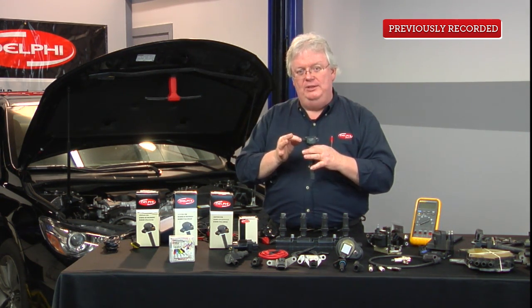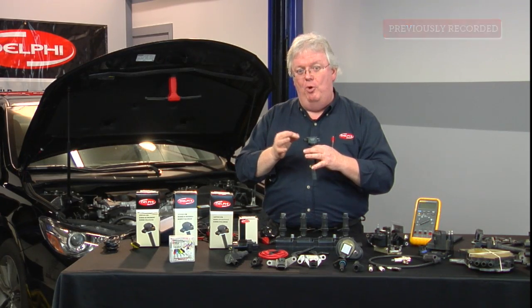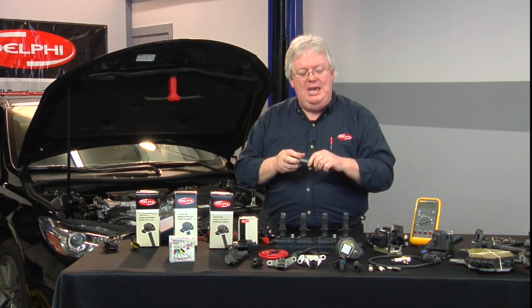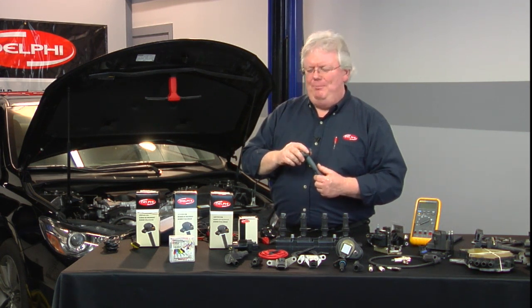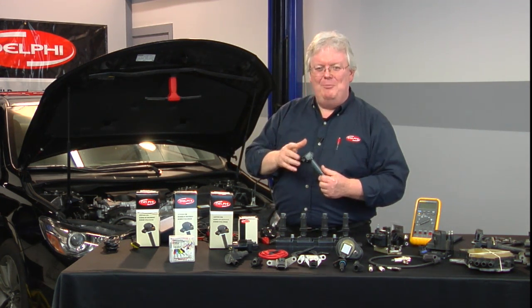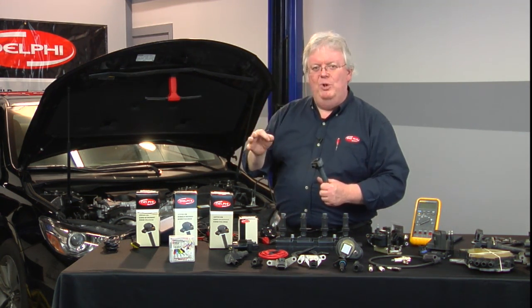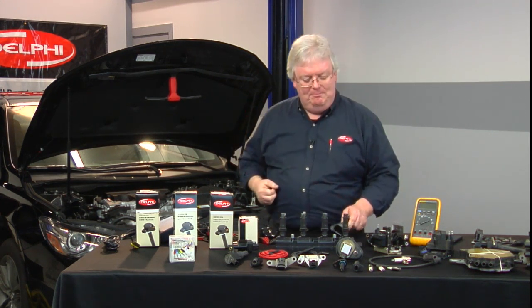You would never want to power them up, power and ground on a bench, and let them cook and heat up like we did in the old days. That's a surefire way to see if you got a bad coil. Yep, you do now. So don't power them up with power and ground. Watch them while they crank or run an engine.